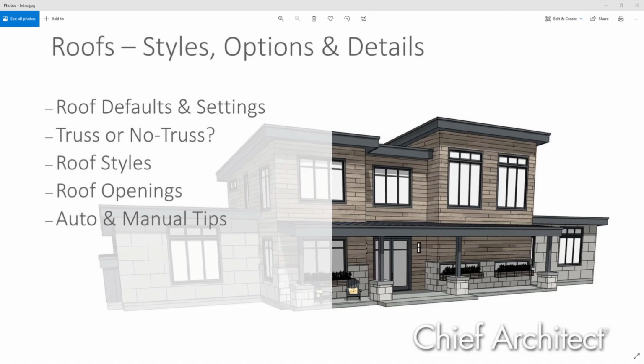Oh, great. So the question is about the skylights. I'm a little challenged with this. Let's take a steeper pitch than a 1:12 because it's going to impact this more. If you draw your skylight in plan, and let's say we're going to make this easy, we're going to make it 2 feet wide, 4 feet in length. When you view it in 3D, the width is the same, but the length is adjusted based on the slope.